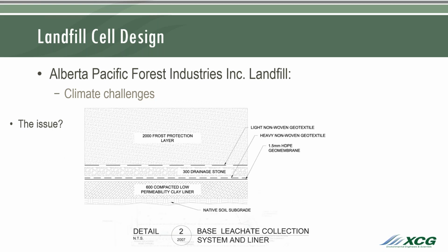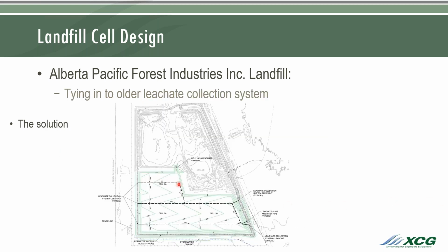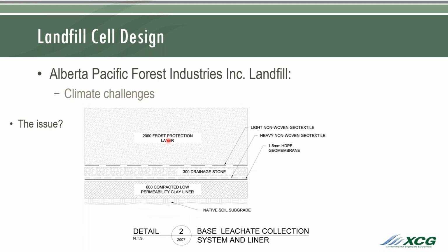And also, the previous slide shows the existing contours being a little bit steeper than their 5-to-1. So the plan is to lay their slopes back to that 5-to-1 and remove some of their stockpiling in areas in order to get to their 5-to-1 and move that excess material down onto the cell floor.